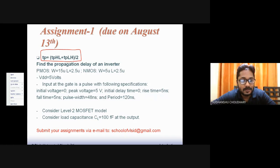Then you will have to consider the level 2 MOSFET model. There are MOSFET models from level 1 to maybe level 50. So what are these MOSFET models? Let us talk about them after this slide. You will have to use these level 2 MOSFET model parameters, and at the output, you will consider a load capacitance of 100 femtofarads.